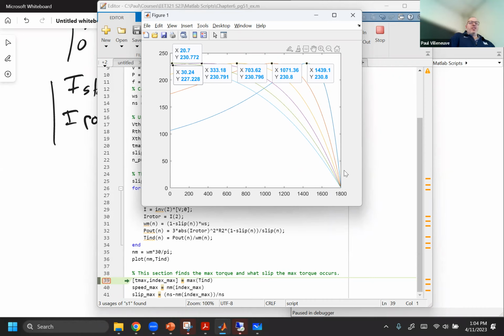But if I wanted to change the speed control and I didn't have a variable frequency drive, I can put in some more rotor resistance and I can get the speed characteristics I want. You can understand why back in the day they would do this, because they were trying to do speed control. If you're trying to control a conveyor and you want to increase or decrease the speed, you would use this resistance value and increase or decrease it pretty easily.